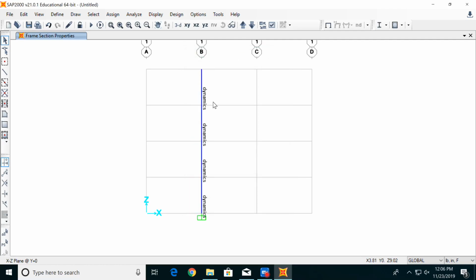One thing that SAP does is it'll label each one of the sections that we made with the corresponding section property. This is really useful when you are creating maybe a beam or a structure that has a lot of different materials composed inside of it. It'll just give you a quick little label to see which pieces are which.